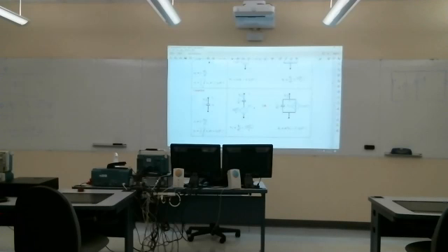And then I have a 4 divided by 8/10, that's 40 divided by the total impedance. I think I did that right. Multiply numerator and denominator by 4S. So here I get S squared plus 4S, and then 4 divided by 0.8 is 5.